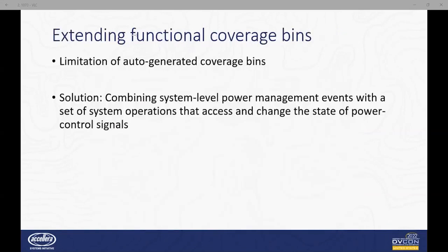The tool is definitely useful to check the power signal itself. However, this approach is not enough to ensure power verification completeness, because we cannot confirm if necessary power events, such as simultaneous or sequential power events, are verified with test scenarios. In real usage, most power events happen with system-level operation. Therefore, we extended functional coverage bins to combine system-level power management events with a set of system operations.